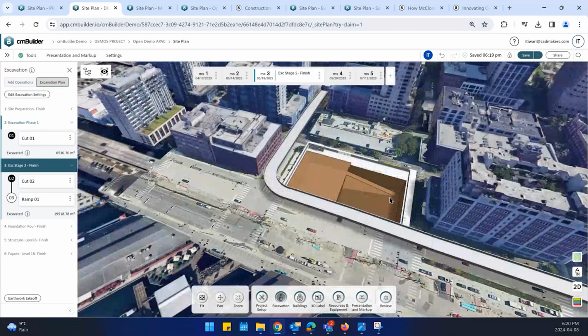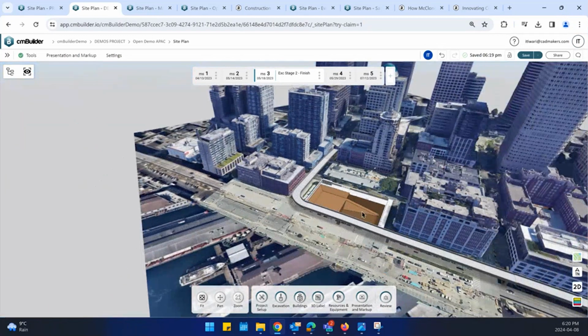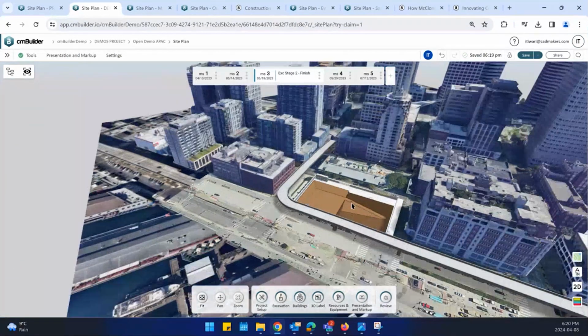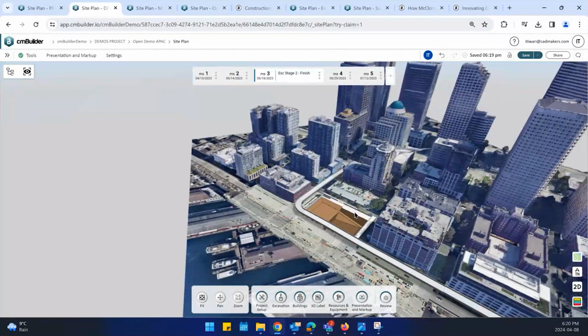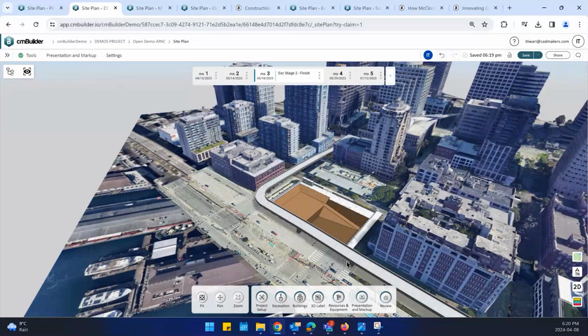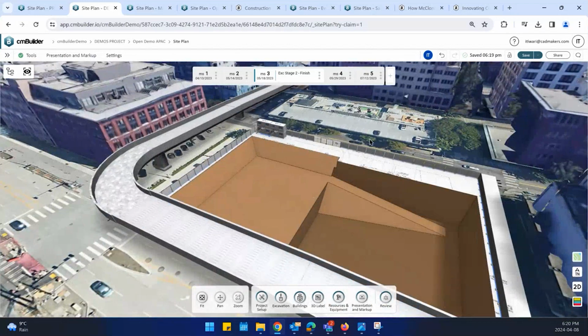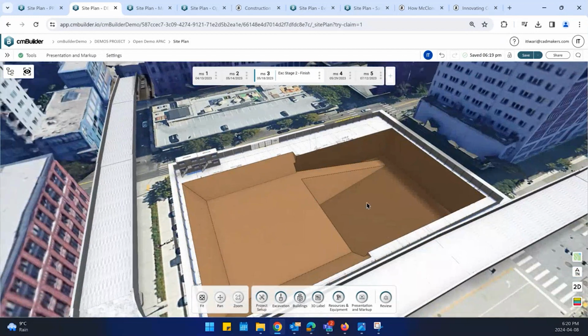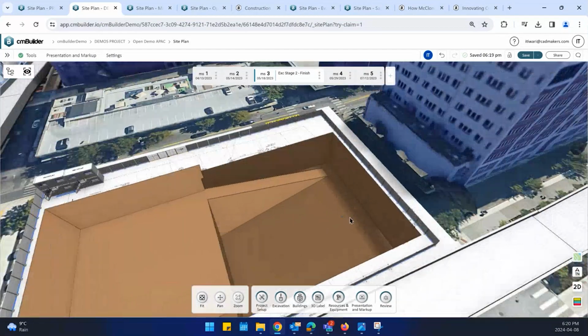And this is essentially where I mentioned that if you do have an updated topography or, let's say, a contour line drawing, we have users using it for updating the topography. Once you have done that, the excavation volumes are calculated from the top elevation of the map. So it's going to give you much more accurate data once you have adjusted the topography, if you want to do that. So it's always useful when you're working with those workflows.